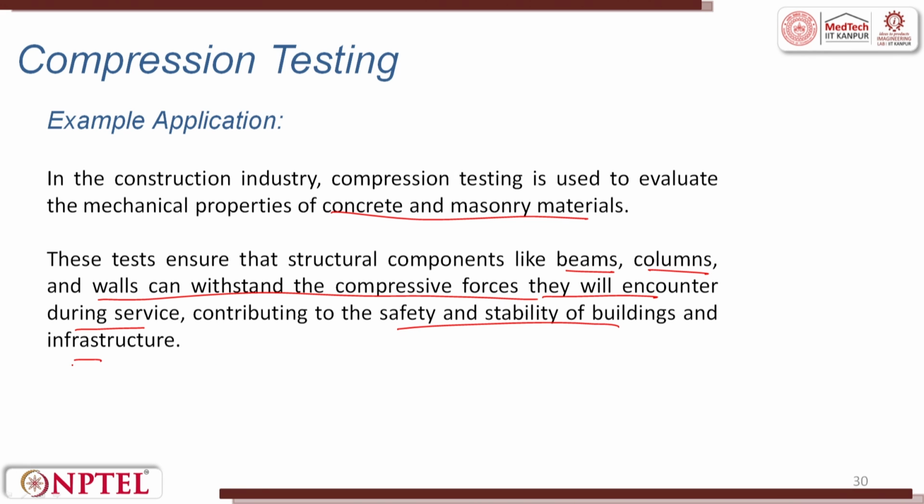Compression testing is conducted for various other materials as well. It is a basic form of mechanical testing employed to assess the response of a material under crushing loads. It is done on the universal testing machine, as we discussed. Concrete, composites, and corrugated materials such as cardboard are commonly employed in load bearing applications, where the ability to withstand compressive stress is of utmost importance.